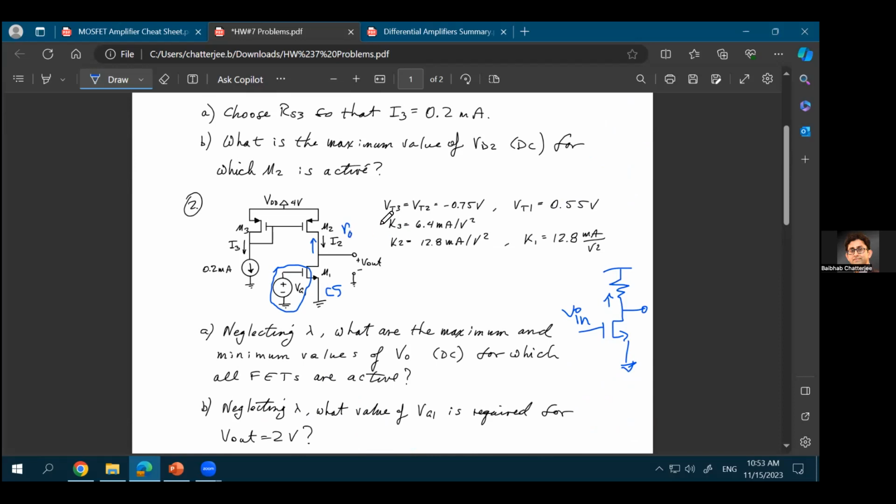Unless the transistor is diode connected. If it is diode connected, you see 1 upon Gm. We proved that as well. But if it is not diode connected, in this case, you have a current source load. This is the way we had defined it earlier, that you have a current source on this side. You are mirroring that current on the right-hand side through this current mirror structure. So this is your current mirror structure.